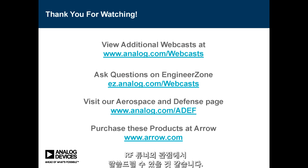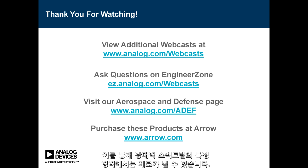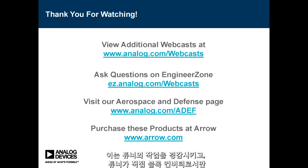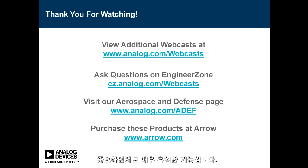So I guess I could take that from the point of view of the RF tuner. Having that function in the chips allows the center frequency that you're looking at to be moved, so you can zero in on a particular area of the wideband spectrum that came in. That makes life easier for the tuner, since the tuner can then just act as a straight block converter, and it simplifies the RF architecture. It's a case of the two things working together to get the best performance, and that's an important feature that's very beneficial.